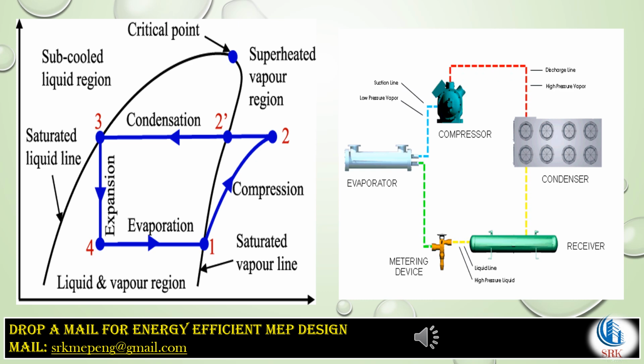When air is blown through this coil from the room or space to be conditioned, the heat from the air is absorbed by the refrigerant. The low-pressure liquid tends to become vapor as it absorbs latent heat of evaporation from the air, resulting in cooled room air. Finally, the vapor is sent back to the compressor to initiate the next cycle. This completes the refrigeration process.